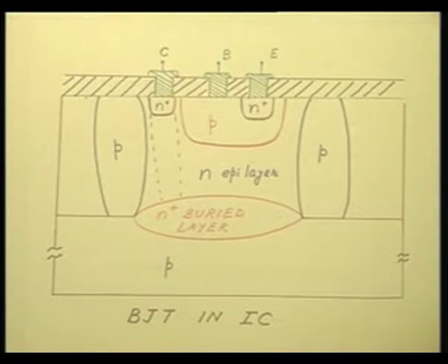This is something you are already familiar with. We started with a p-type substrate. Normally we used 111 substrate. Remember, it is a comparatively older bipolar junction transistor. So, in those days still 111 substrate was considerably cheaper than 100 substrate, because now you know that it is much easier to grow 111 crystal, right.